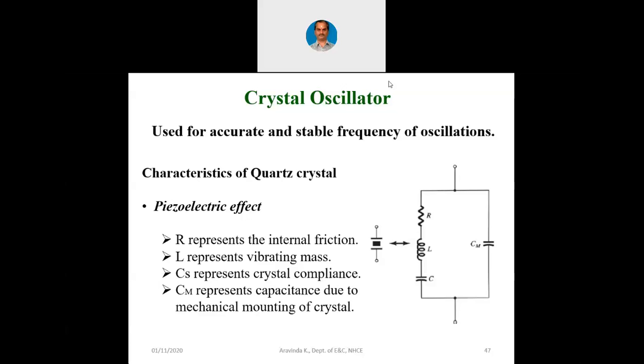Okay. Output of the divider is now 1 hertz. That 1 hertz is now 1 second. That 1 hertz pulse is shown either on the LCD display or it is given through some other electromechanical arrangement to the needle which is moving in seconds. So that is how our regular wristwatch is going to display the time.